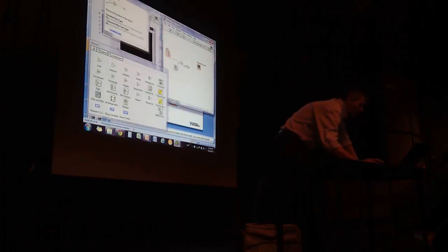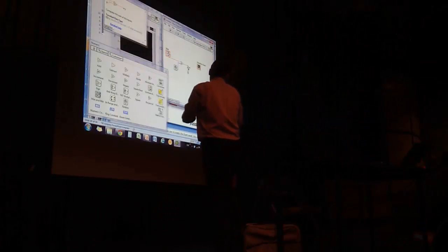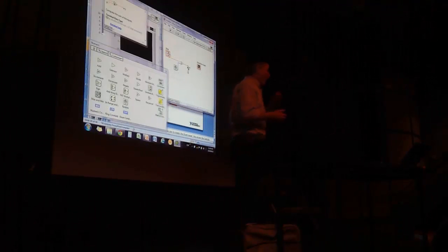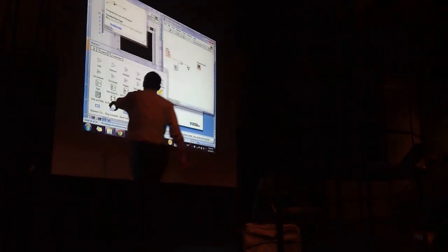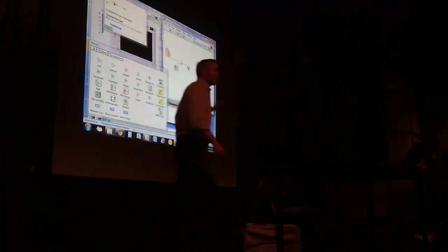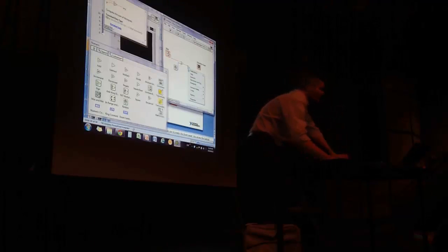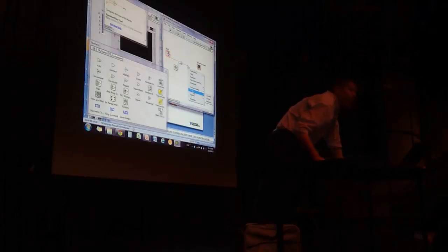So I click it here and I connect it over here. Another important thing that I want to show with this example is how you can create just inputs. What I can do, of course, is pick a numeric constant and drop it in here and then use it. Another way to do this more elegantly and faster is to right-click on this input and you see here, create.